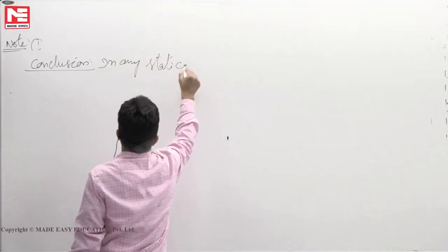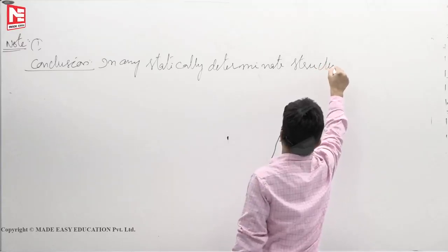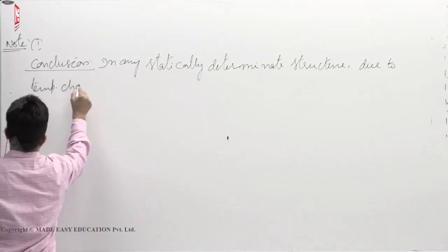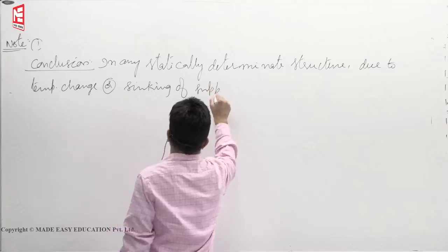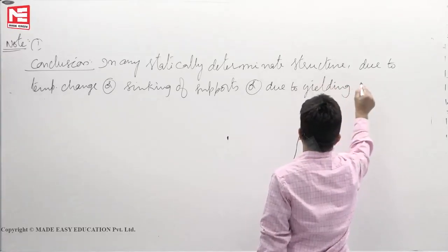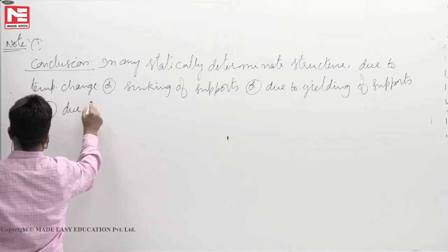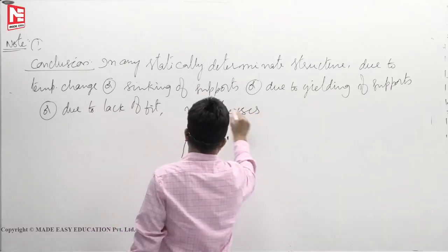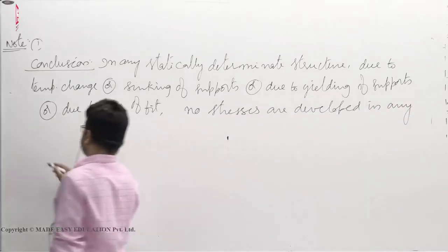In any statically determinate structure, due to temperature change, or sinking of supports, or due to yielding of supports, or due to lack of fit, no stresses are developed in any part of the structure.